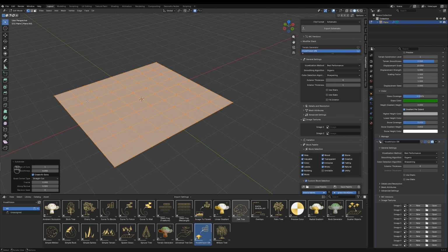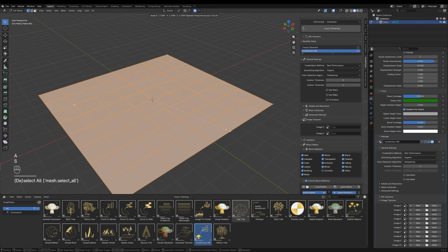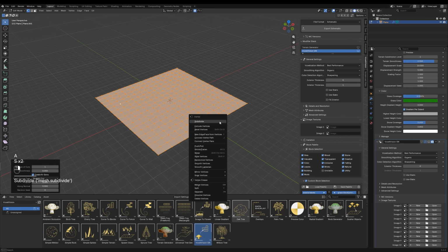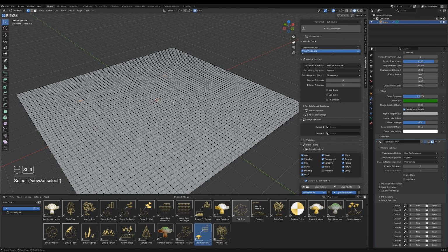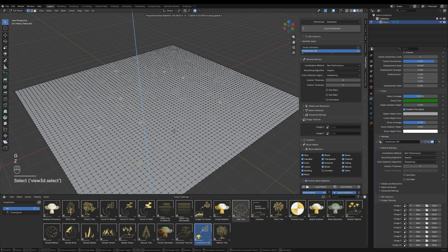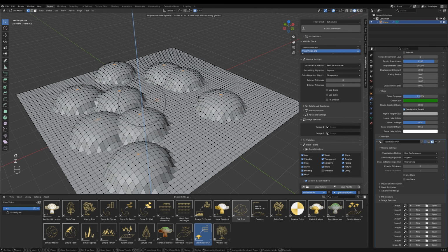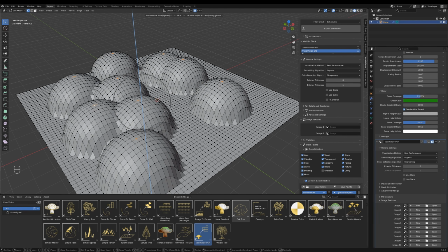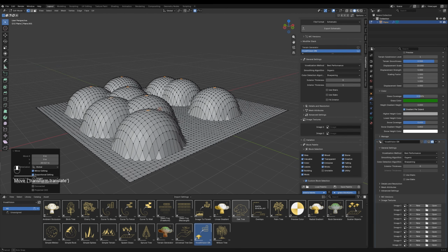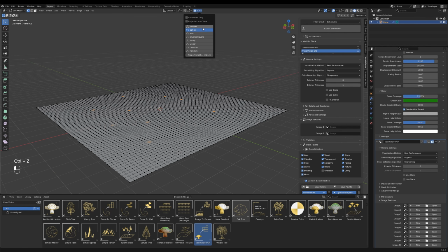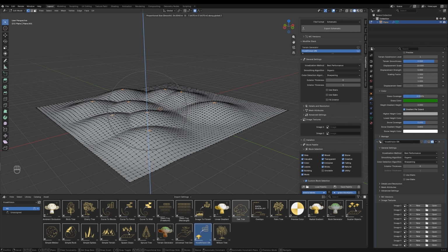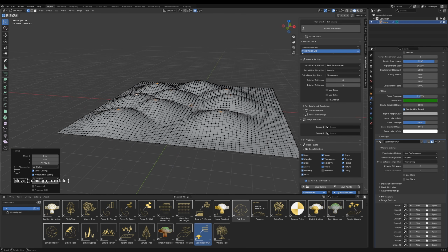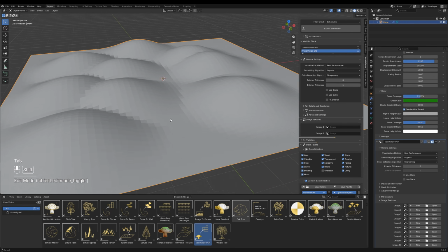And then we can basically go in, let's scale it up a bit, subdivide even more. And then we can go in and select different kinds of points, use the proportional editing, and then you, for example, get something like this, which is pretty cool. So you could do little hills. You could also choose a different falloff, for example smooth, then it's more of a hilly side. And I mean, this is pretty stupid, quote unquote, but this is the base that you can work on.